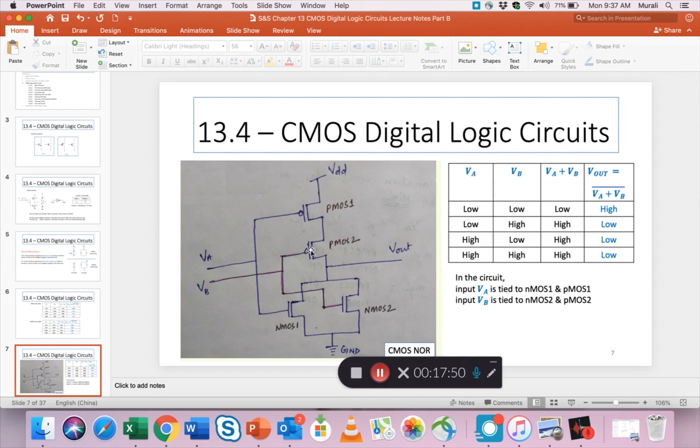And so to do that, we need 4 transistors, 2 NMOS and 2 PMOS. And how should you connect them so that you can get exactly this truth table that we just studied, right? We want all this to be truthfully implemented or executed by this circuit. And so you can try various combinations, but this is the combination that works.